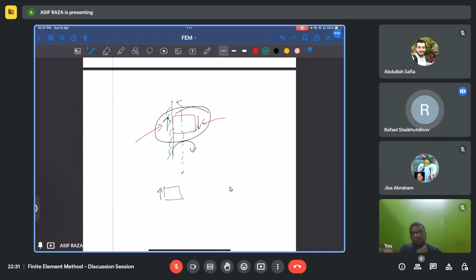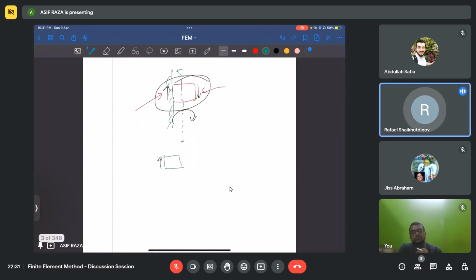Okay. In a pure bending condition, this force is equal to zero. So if we have a transverse force, my answer is yes. In this case, we have a shear deformation and shear stresses because we have a force there. We just divide this force along the area and we produce a shear deformation.